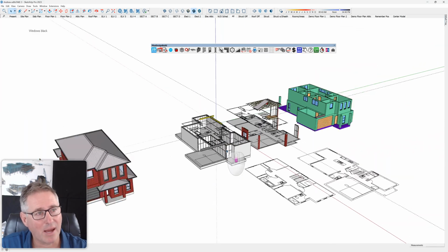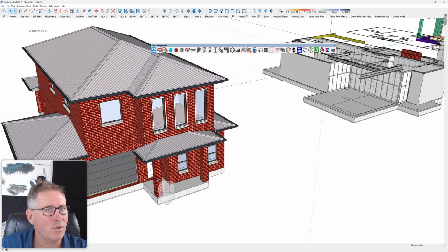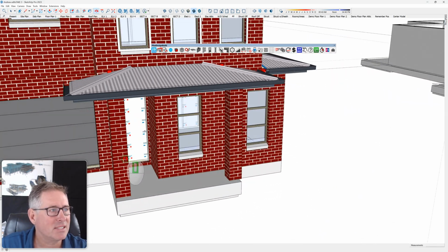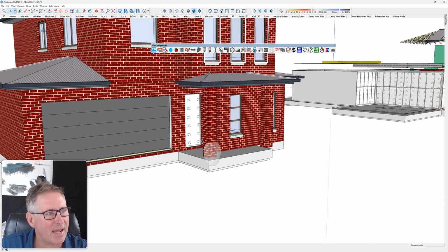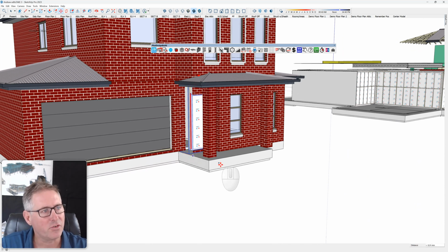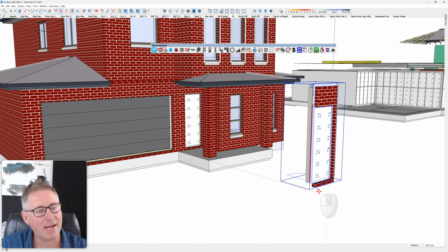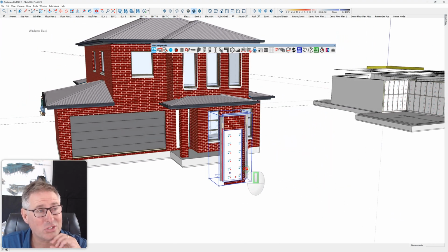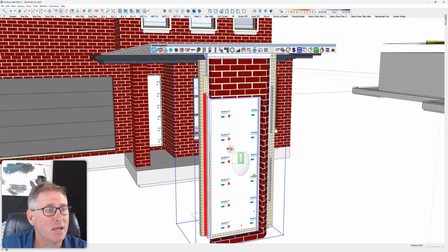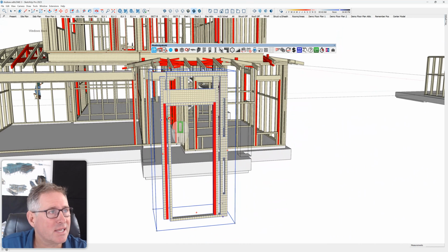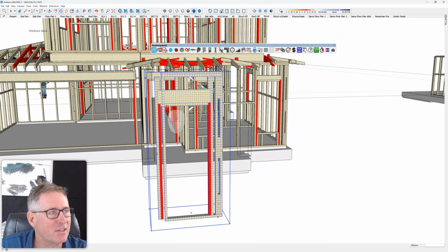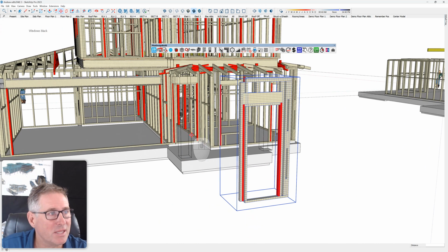Now there was one other problem that I did notice in Matt's model, and that is the front door actually has a texture running through it. And for me to understand how that happened, I need to move this wall out and have a look at it. I'm going to move, control, and bring it out. Now this is something common that I do see from new designers, guys. When I looked at it in structure mode, I can see that the wall wasn't long enough to fit the door in, so he's drawn the wall in anyway, and it clearly showed me there was a problem here.